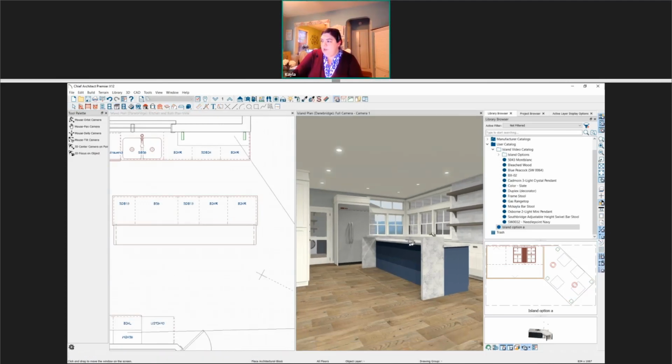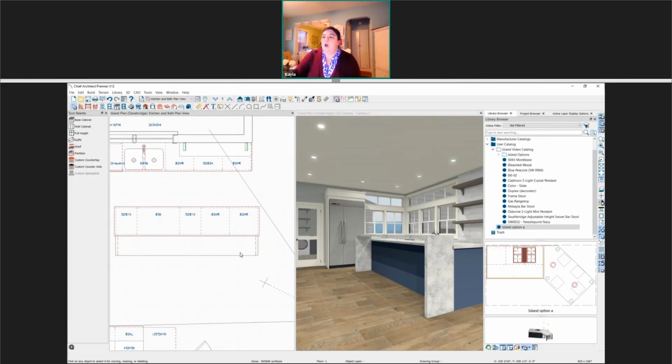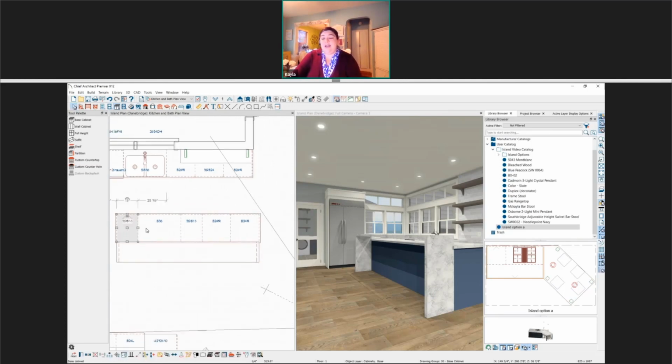All right, and if you look here, I need to add essentially a waterfall to the back, but I don't want it to go all the way down because we're going to add some panels to the back of these cabinets. So to add in the gap between our cabinets and our countertop, I'm going to use the backsplash tool that's built into the cabinets themselves.